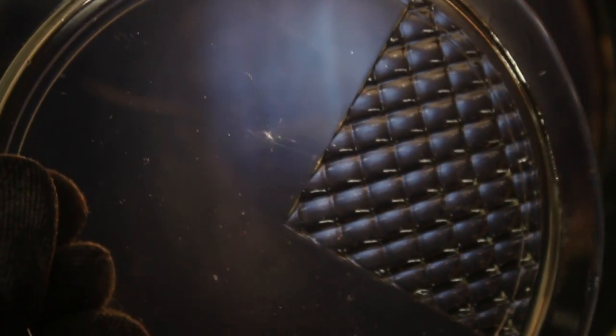Glass with erratic stress will show high contrast in light to dark areas as seen in this part under the polariscope. Glass with controlled stress will have uniform shading when viewed through the polariscope.